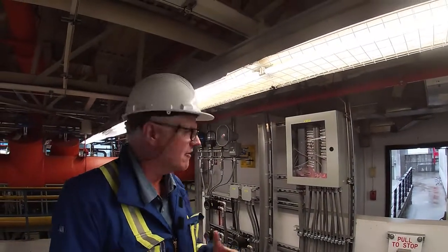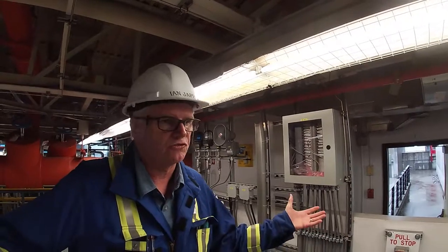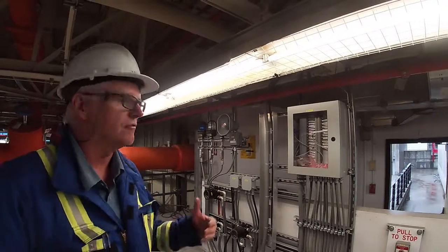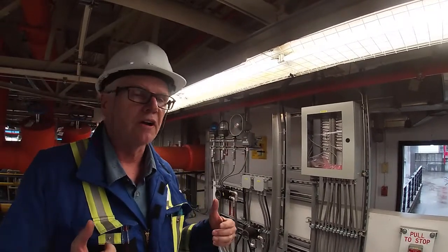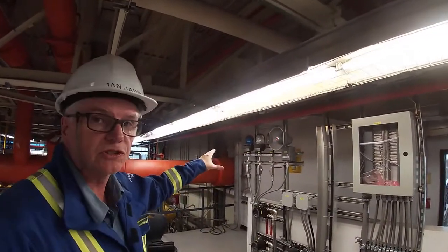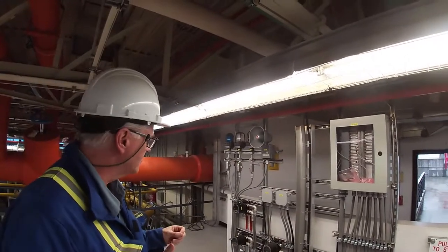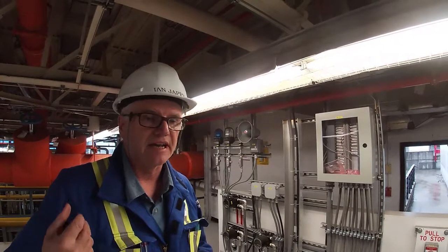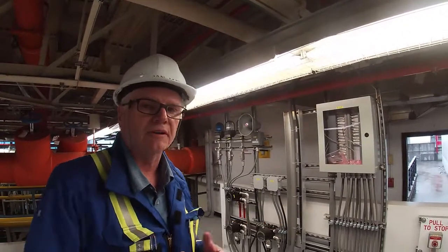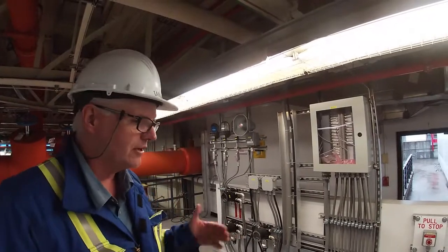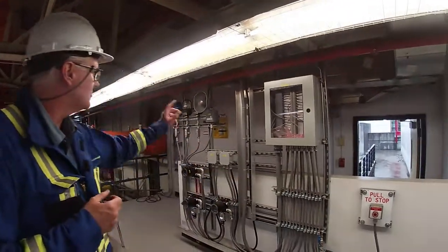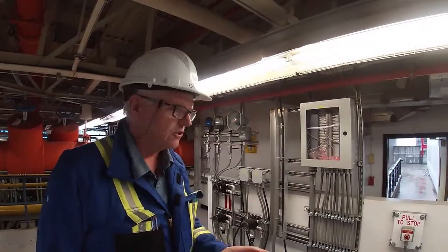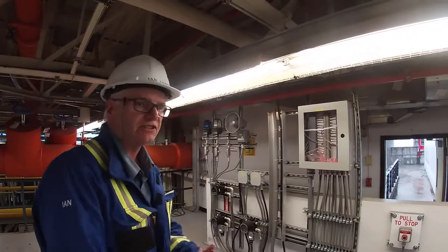Now you might be asking, how come we have 3 different colors? Why not just one strobe? Well, if you're in operations, you'd want to know what happened. If I was an operator in the field and an alarm went off, and I saw a blue strobe and the horn going, I would say, oh, that's toxic gas, so I better get out of the area, suit up, and come back out and sniff the area. So operations would want to know. If it was an E-stop and you see all 3 flashing, you would know somebody hit an emergency stop. So that's the basics of what we have for our SIS system.